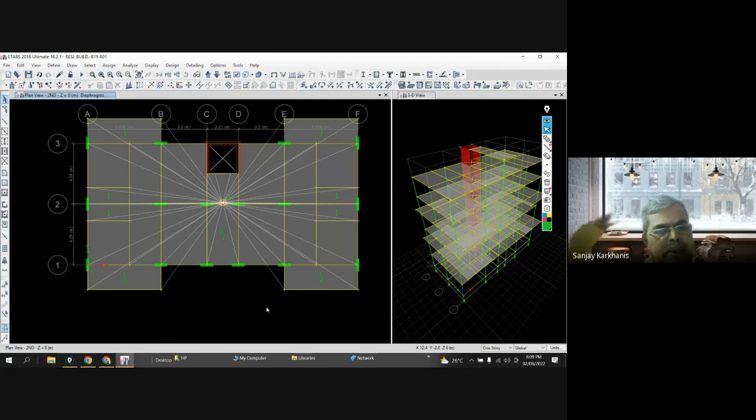Now, in many videos, they will say select all the slabs and give the diaphragm D1 to everything. But I will not. See here this red dot, which is imaginary, for your understanding, is created, and all the corners are rigidly connected to this body. So the movement of this point will be exactly like this, D1. That is the concept that shows you a rigid diaphragm.